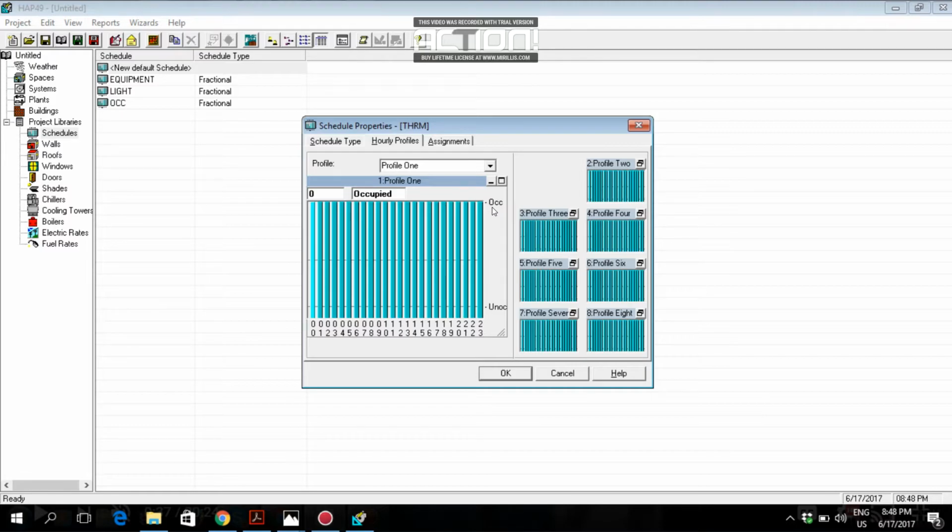So the thermostat will switch the machine on and off depending upon the set point of the area. For example, if you set the point at 20 degrees centigrade, with minimum temperature 20 and maximum temperature 24 degrees centigrade, once the room temperature reaches 20 degrees, the thermostat will turn off the machine because you don't want further cooling.